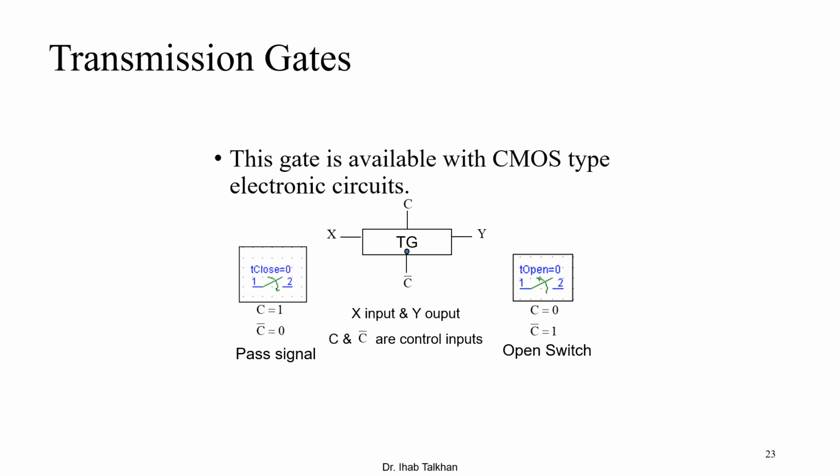We are going to use this type of switch in order to build all the gates that you have used before, which means the XOR, the XNOR, NAND, the NOR, whatever. We can use these four components: the transmission gate, inverter, power supply, and the LED. With these four components, you're going to build all the necessary gates, as you're going to see in the next slide.